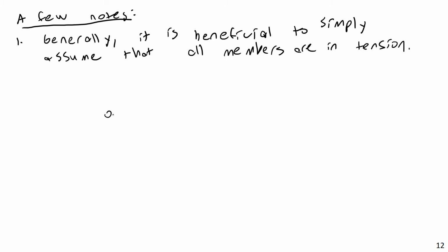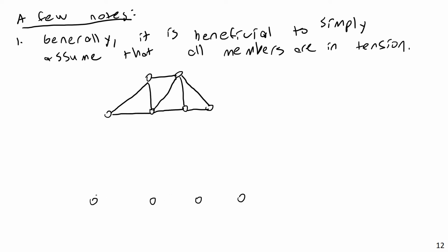So if I have a truss here, I'm going to divide it up into an exploded view with all the member forces, etc. Like this. Oh, actually, maybe I don't want to show quite that many members. I want something that I can draw out relatively quickly. When I draw this into an exploded view and show all of the forces that are revealed, I generally just go ahead and assume that everything is in tension.